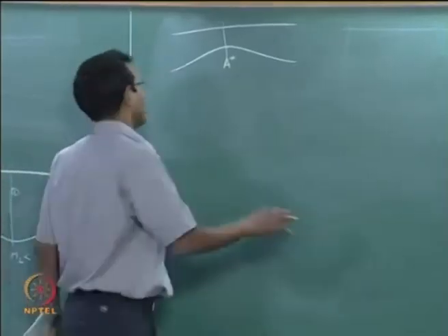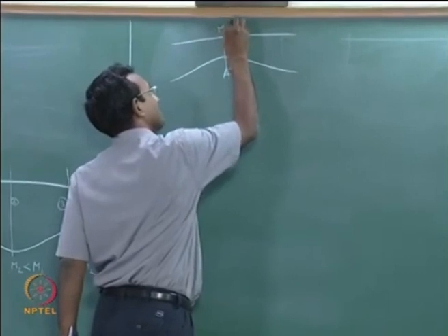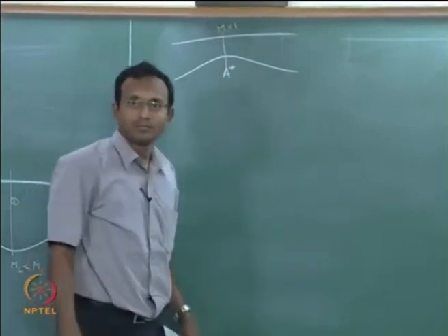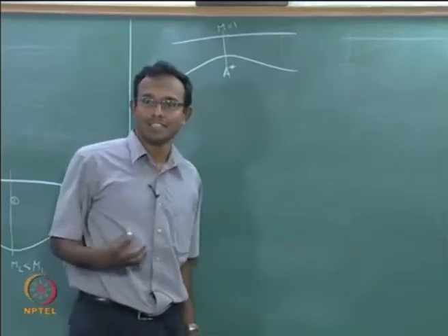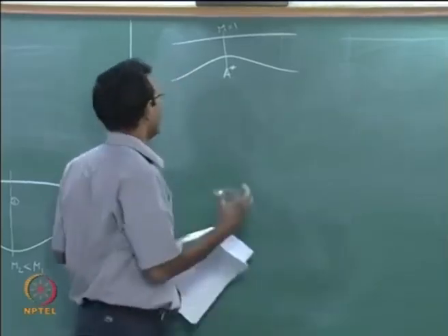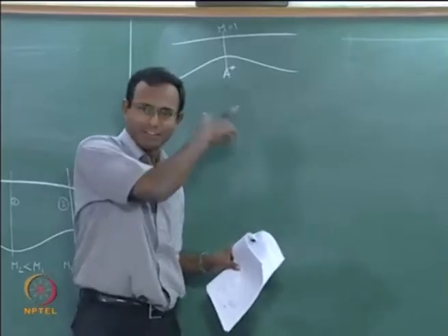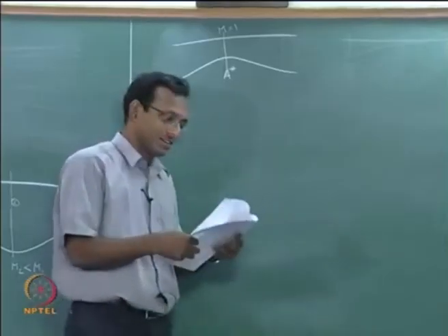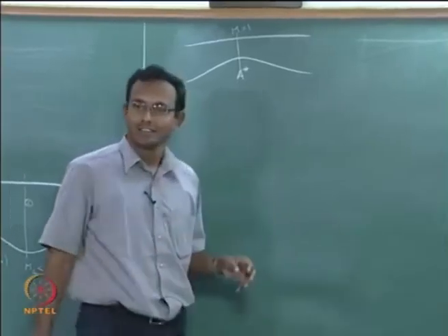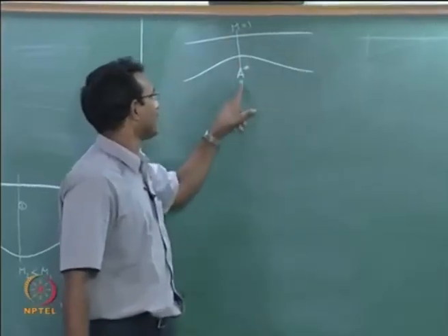Okay. I know that it is choked area, which means my Mach number here is 1, okay, because that is by definition choking for me. I want to say the least area point and it is choked, I am going to say. We will go and redefine that choking more after we have done some derivation. Okay. As of now, we will just assume that it has to be the least area or the minimum area possible, and we will assume that Mach number is 1 there.